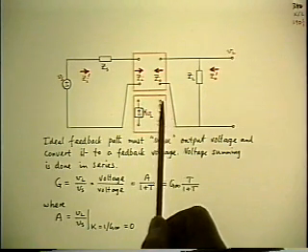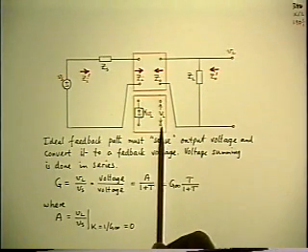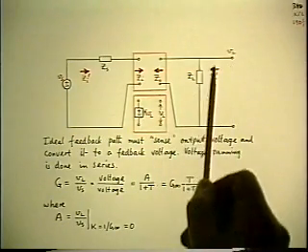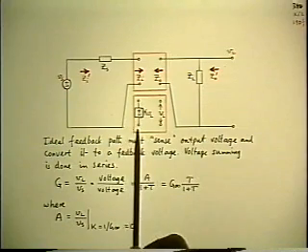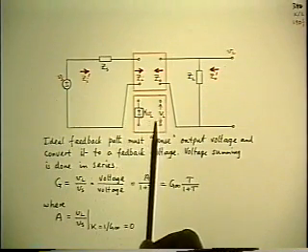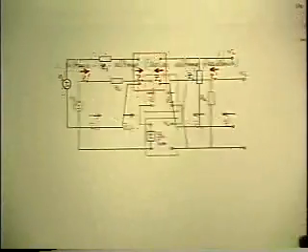So that tells you right away how you have to connect this feedback path. You've got to connect it so that the voltage between the two input terminals of the feedback box is the same as the output voltage. So obviously you have to connect it in parallel with the output. And at the other end, the fed-back signal is a voltage, and you have to do voltage differencing with the input. The way you do voltage differencing is by connecting in series opposition. So that tells you how you have to connect the feedback path at each end.